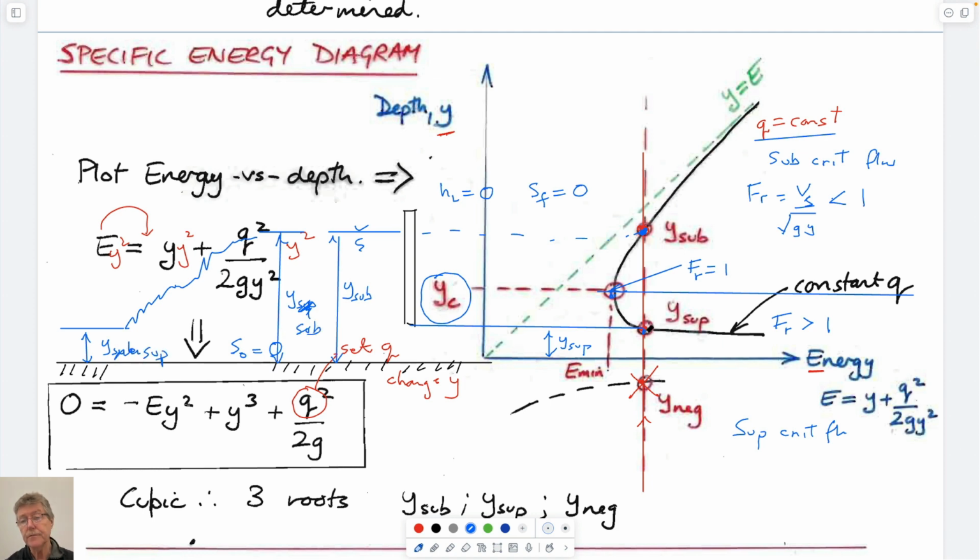So it starts off with this. To go from here, at the upstream, to here, it has to go along this curve, because at any point that we take along here, the flow rate per unit width has to be the same. This value, Q, has to be the same. And so usually to be able to do that, we have to supply something to do it.